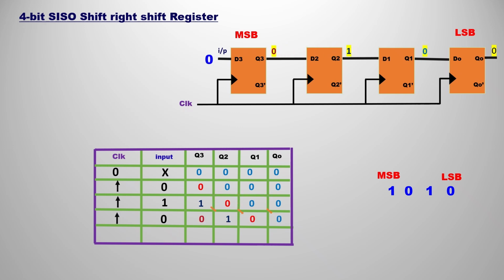The next thing in our required thing is 0. So that is the bit for the MSB. So again you are going to push 0. You can also observe that again the red 0 is shifting towards the right and the 1 is also shifting. The new 0 is inserted in the Q3 position and again the Q0 position is popped out.